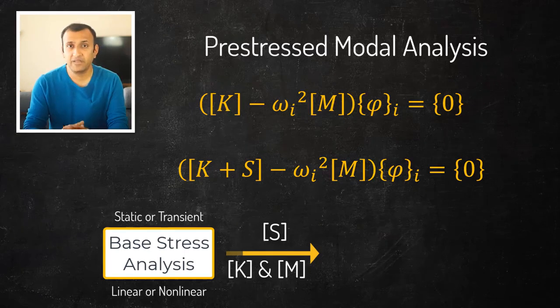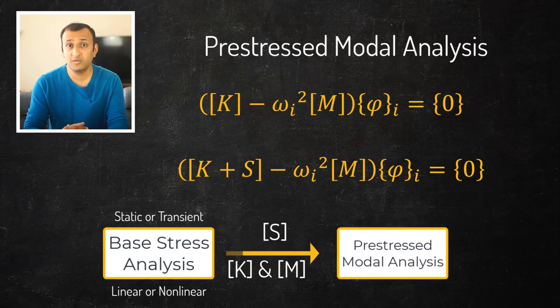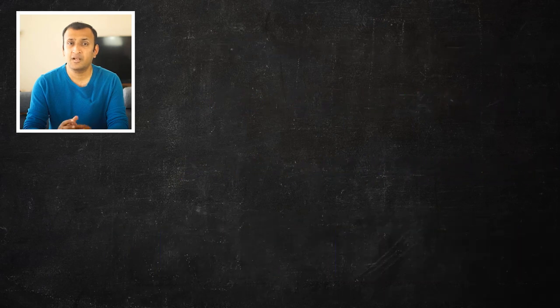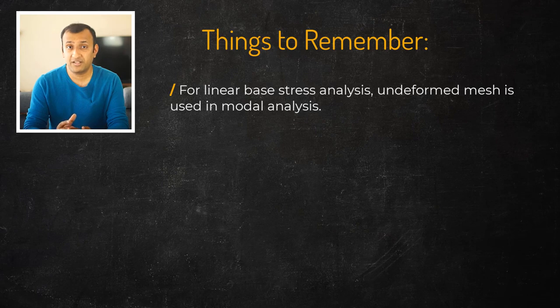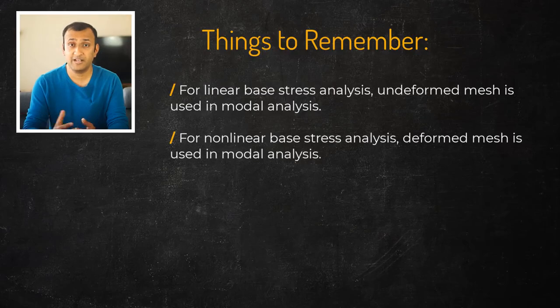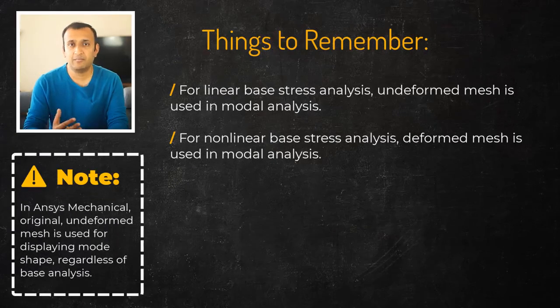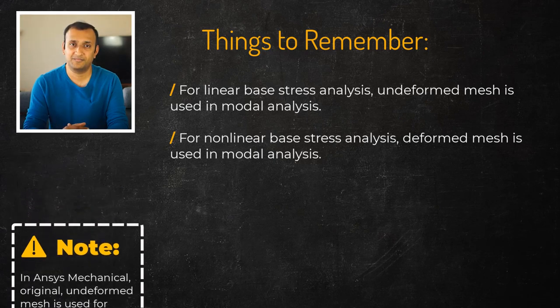In Ansys Mechanical, we restart from the base stress analysis and use the linear perturbation technique to perform pre-stressed modal analysis. A few things to remember about pre-stressed modal analysis are: if the base stress analysis is linear, then the modal frequencies are calculated with respect to the undeformed mesh. If it's nonlinear, then the mode frequencies are calculated with respect to the deformed mesh. Also, any changes in stiffness and mass matrices due to material or contact nonlinearities are captured at that moment and updated during the modal analysis.